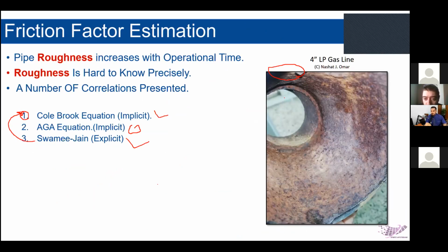Whenever you have corrosive fluids or corrosive gases inside your hydrocarbon, there is chemistry going on here, and it will start to peel the iron, and you will have metal loss. Whenever you have metal loss, for sure, this metal loss will not be uniform. So you will have corrosion patches here and there. It increases the inner wall roughness, and whenever this roughness increases, you get high uncertainty.